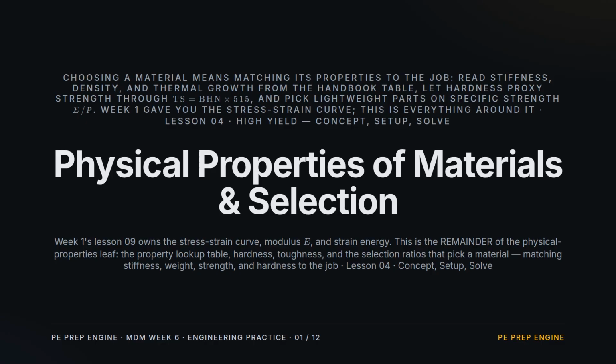Week 6, Lesson 4, Physical Properties of Materials and Selection. Back in Week 1, you built the stress-strain curve, the modulus, and strain energy. We do not repeat those. This lesson is everything around them: the property table you look up, hardness, and how it stands in for strength, toughness, and the selection ratios that let you pick the right material for a part. Choosing a material is matching its properties to the job.